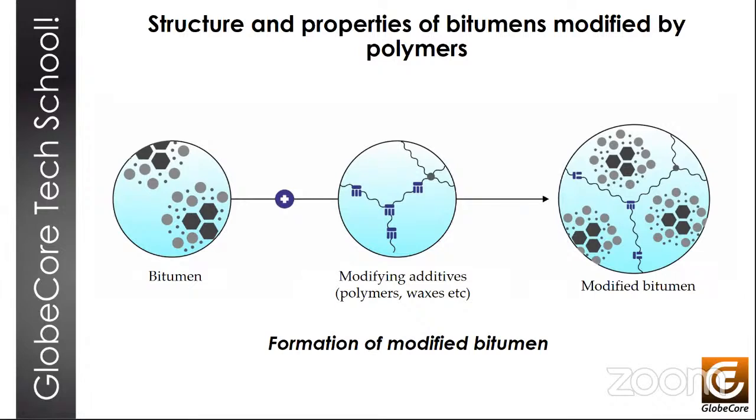At low polymer concentrations, the compositions can be considered dispersion strengthened. In this case, hardening occurs because fine dispersed particles impede the movement of dislocations in the matrix bitumen. The degree of hardening is proportional to the resistance of the particles to the movement of dislocations. And this effect is observed most when the content of the dispersed phase, i.e. polymer, is 2 to 4%.